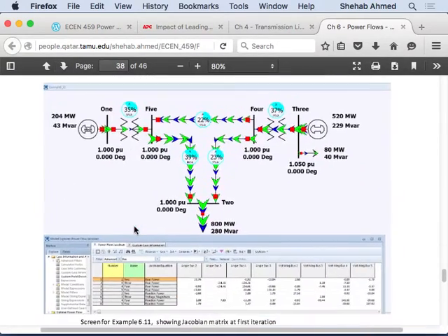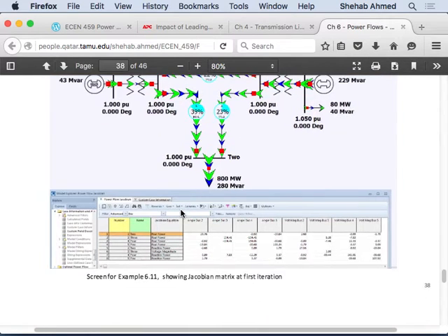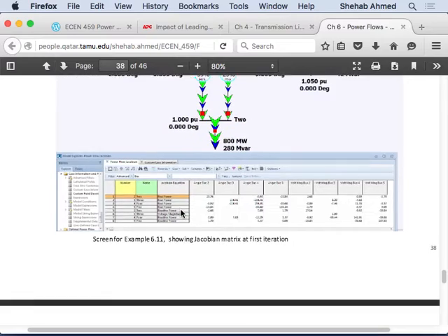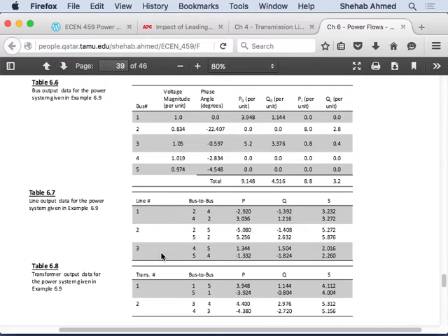This is an example of how you can study, and this example is solved for you. But this is a 5-bus system. If you want to make a 5-bus system, you can do that. I prefer a small system, 3-bus maximum, which is easier to solve manually, then with a calculator, and then with PowerWorld. This is the only thing you need to do for studying this chapter, for the most part. There's some theoretical stuff that we will still cover, but this is the core of this chapter. And this is the solution manually that is also extracted from PowerWorld.